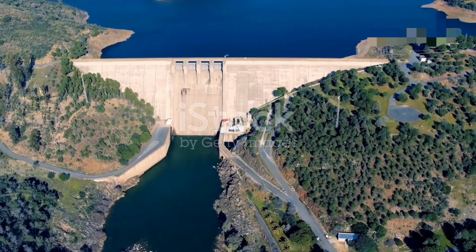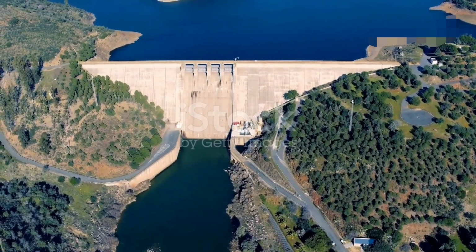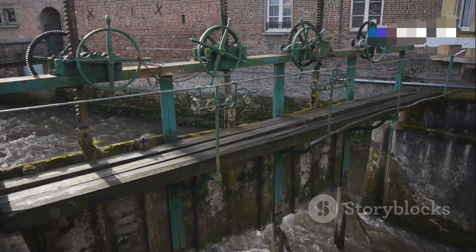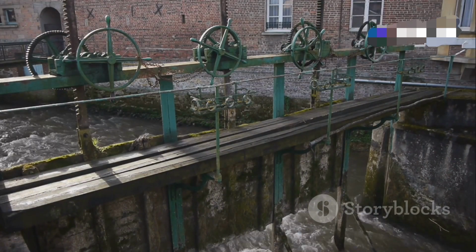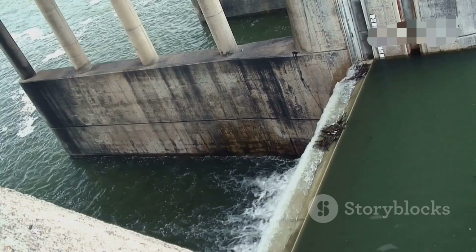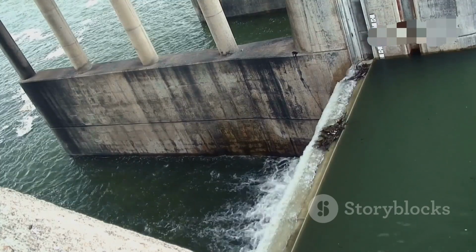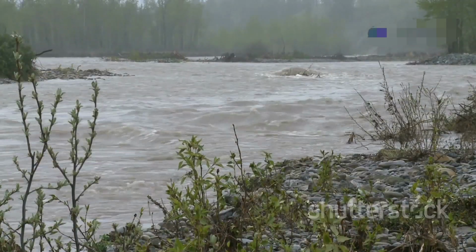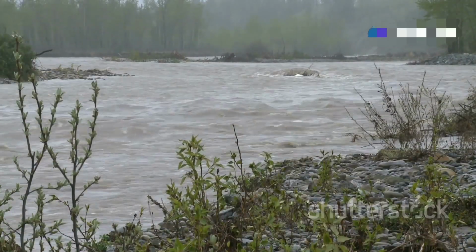Section 6. Breach development time, the pace of catastrophe. Breach development time, often denoted as TF, is a critical parameter in dam break modeling. It represents the duration it takes for the breach to grow from its initial formation to its full, final dimensions. This time frame is incredibly important because it significantly influences the characteristics of the resulting flood wave.